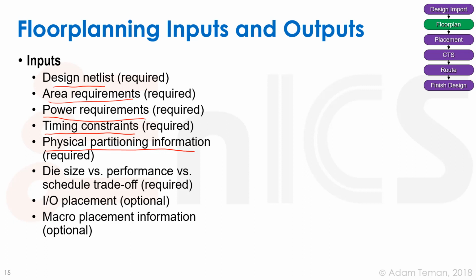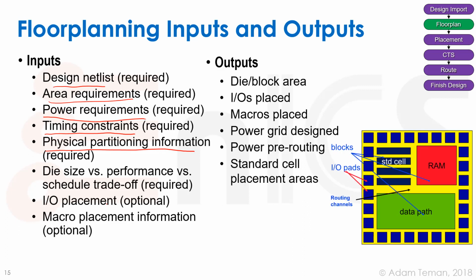I/O placement, well, if we're talking about a whole chip, we're going to have to put those I/Os, and usually the I/Os will have to be put where they should fit on the board or in the package. But sometimes we're going to be talking about a smaller block, and we just have to discuss where to put the pins that actually let us get in and out of the block that we're dealing with. Macro placement information, this is a good question, and we'll discuss in a few moments how we decide where to place our macros. So those are basically the inputs to our floor planning.